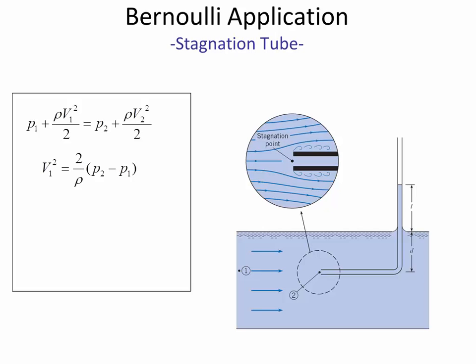So inside the tube, it's just the same hydrostatic equation that we've always seen. We can find the pressure at location 1 as a function of the depth. And here they're saying gamma d. That's the same thing as when we say delta H times gamma. You'll notice that d is just the dimension that they're applying to the depth below the water surface.